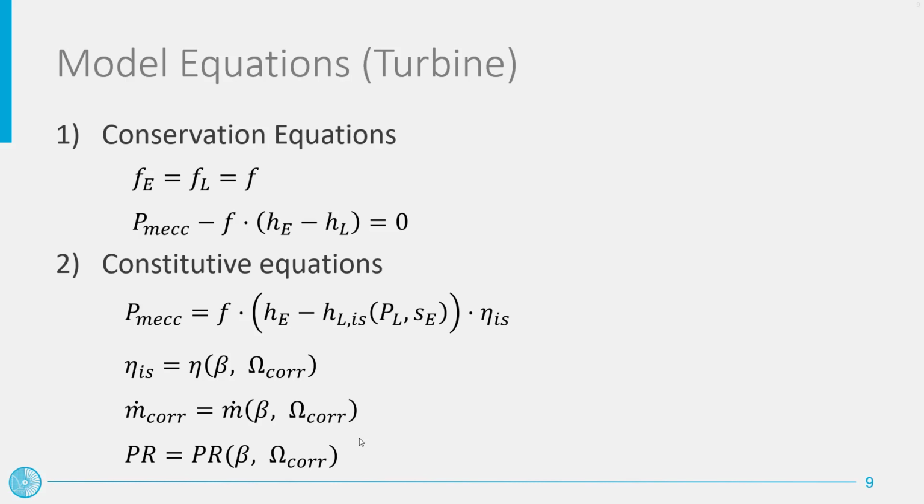In addition to these constitutive equations, to close the turbine model, you have to consider the relation defining the reduced speed, the equations to calculate the thermodynamic properties of the fluid, and the equations defining the model interface. In this respect, I invite you to have a look at the code of the models for turbines and compressors in the Modelica library BasicAeroEngines that you can download with the exercise of Module 7.